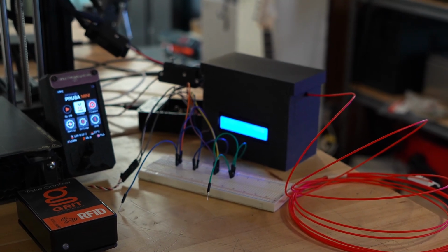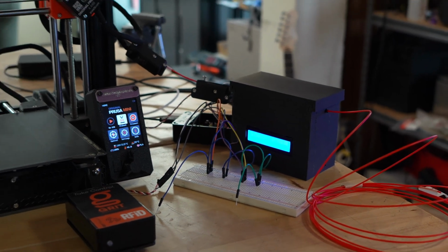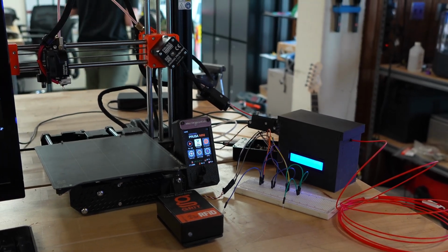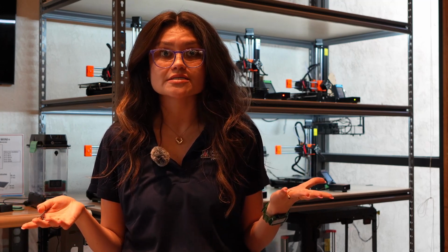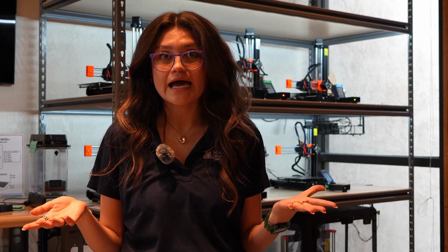Selecting the correct material type is critical since each plastic has a unique temperature and speed setting. Our team was tasked to create a system that identifies common filaments such as PLA, ASA, and PETG using spectroscopy and automatically adjusts the printer settings if a mismatch is detected between the filament loaded into the printer and the filament the user has selected, with 75% accuracy.